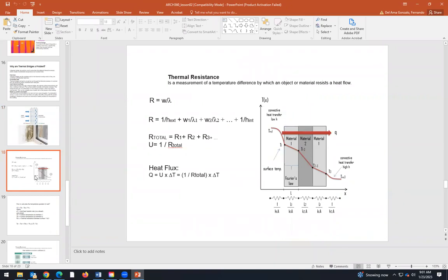So what can we do? Or how can we apply building science to prevent this from happening? The first thing we need to know, and this is what we are going to do today, is to analyze the temperature within the wall. This is the indoor temperature, the comfort temperature, around 70 Fahrenheit. This is the outdoor temperature, which can be 20 Fahrenheit in winter.